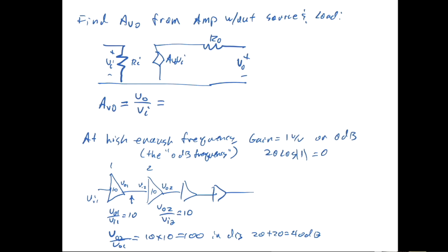Some of what limits the speed of the transistor are the resistances and capacitances in it, and sometimes we can lump those all together into a single equivalent resistance and a single equivalent capacitance. Then it's like a single time constant circuit, like a low pass filter. So at a high enough frequency, even if the transistor could respond, that response is filtered by that RC time constant.